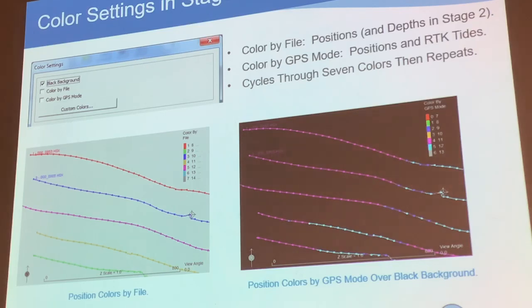That means when you see GPS quality 4 or GPS quality 3. If it's GPS quality 1 or 2, that means you are not getting a high quality GPS, you're getting a low quality GPS. That means your position might be wrong. There are different codes for your GPS, 1 to 5. 1 means it's just standard, and 2 means it's using DGPS, differential GPS. 3 is post-process kinematic. 4 is RTK.